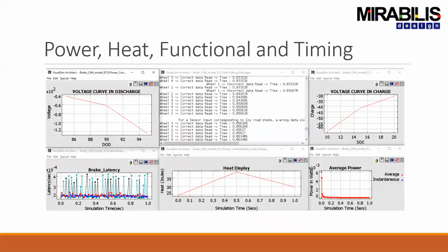Now, why is that significant? The reason it's significant is because I'm not just dependent on the ECU. The application goes beyond the ECU. It goes to how the sensors are positioned, or where the sensors are positioned. It looks at where the ECU processing occurs, whether it's happening closer to the sensor or closer to the ECU. And also other attributes such as power consumption, heat dissipation, voltage, all of that type of information starts playing a major role.